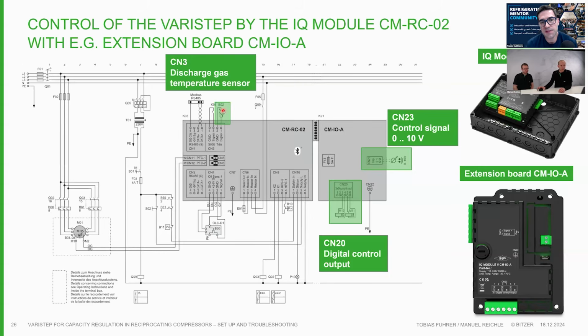So is that a specific sensor? Is it a 10K and 86K? Is it a specific one for that one? Just say one fails in the field, they check the resistance. What would the replacement be for that sensor? And does that come with it? Because I think I tell every technician, you got to be putting discharge protection on your compressors, because if you get overheat, the compressor is going to die, and it costs a lot more money than a $20 or $30 sensor or whatever it costs. You know what I mean?